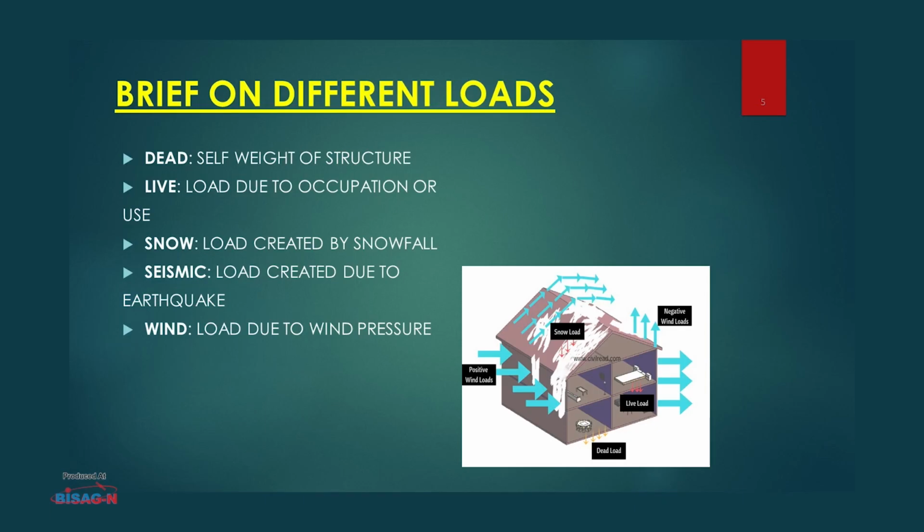Before we understand the various types of design loads in detail, let's briefly understand them with the help of this slide. Dead load is due to the self weight of the structure, whereas the live load is due to occupation or usage of the building. Snow load is created by the snowfall accumulated on the surface of the building. Seismic load is created due to the earthquake, and wind load due to the wind pressure on the surfaces of the building.